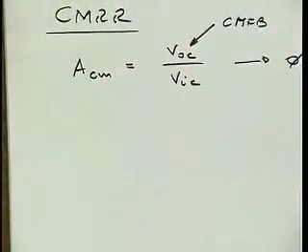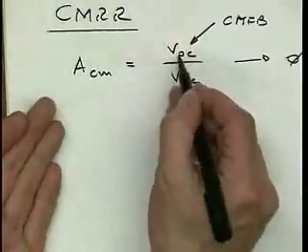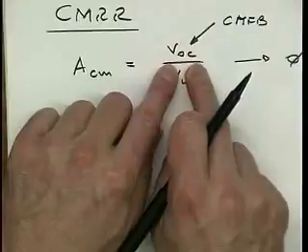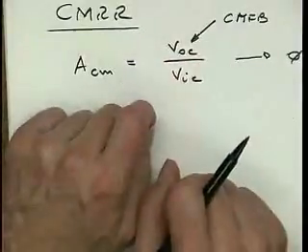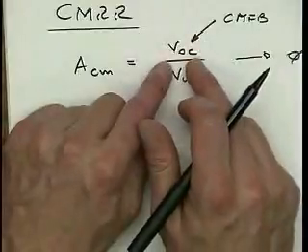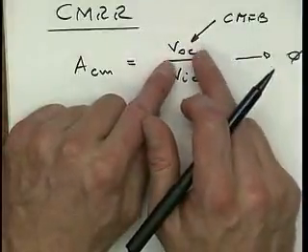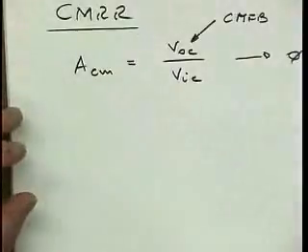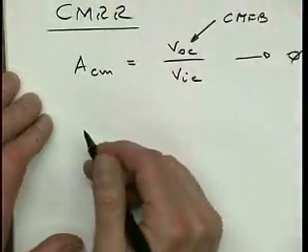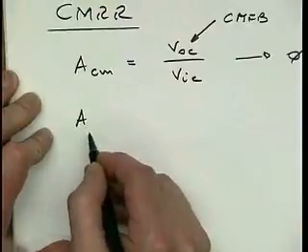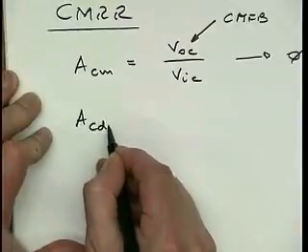Also, this figure is not that interesting because hopefully the next amplifier that we stick this signal into has a good common mode rejection ratio. In other words, it doesn't look at this signal, it looks at VOD, and then a little ripple on this really ought not to hurt things too much. So then the other one that is very important is the ACDM.